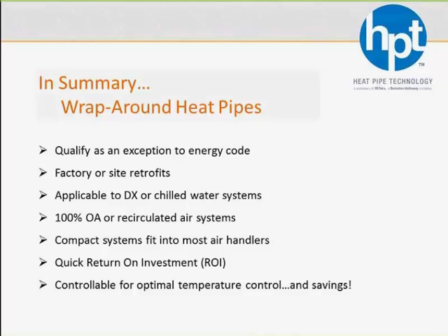I mean, obviously the examples I gave might have appeared on the little extreme side, but even if we're just adding 5 to 10 degrees of reheat in a climate that's certainly not as favorable as here in Florida, you're still going to see, again based on utility rates, return on investment somewhere in the 2 to 4 year range, generally speaking.